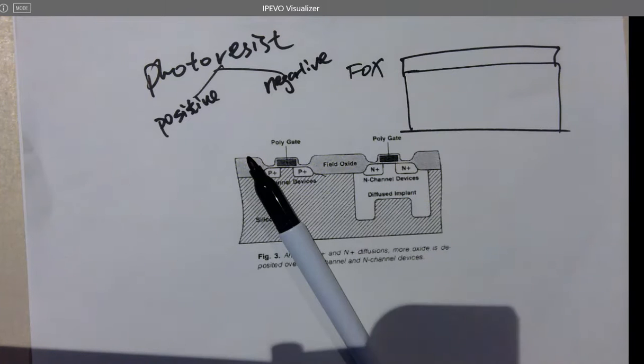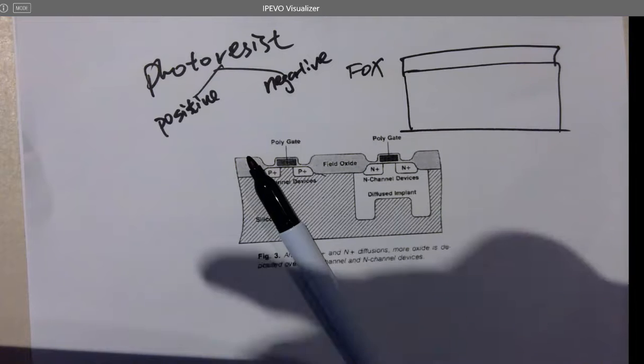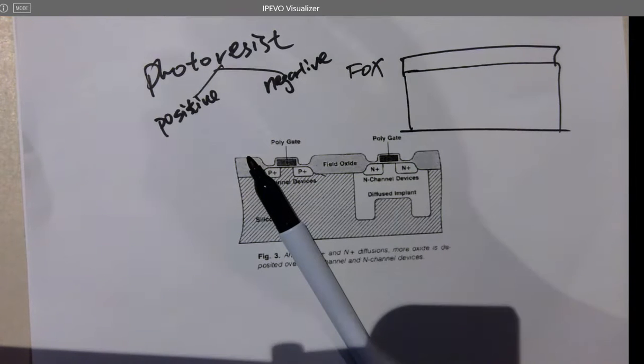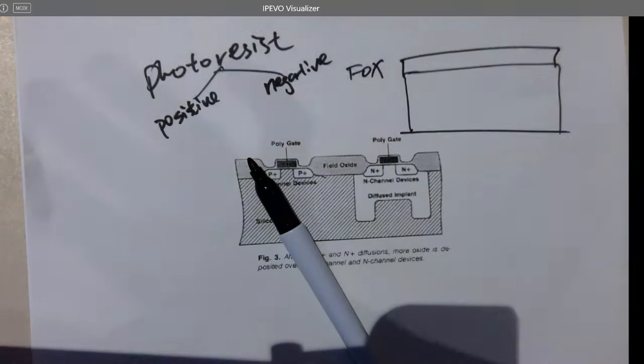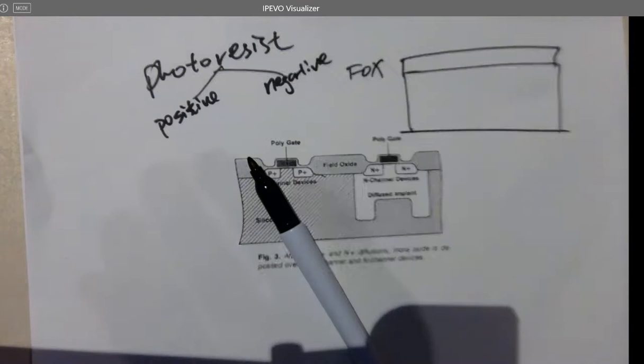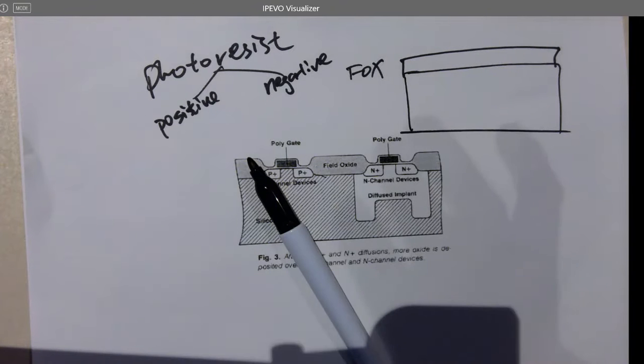So what's happening is these circuit layouts will be printed out as a GDS2 file. It's a format that can be directly printed out on the masks. So the mask can be printed on the glass plate, which is a more expensive mask material.